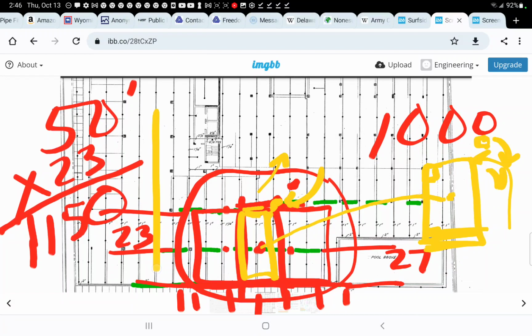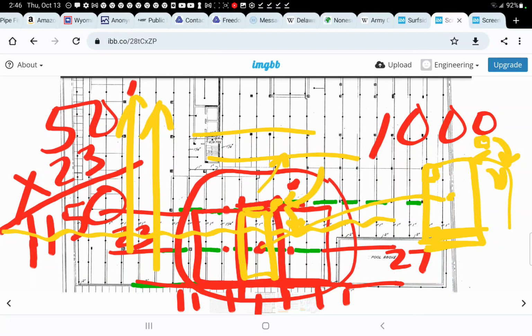Remember, the reinforcement really matters in here, how this is done. It's a number 4 there, number 5 overlapping, high, low. It really matters in the behavior, where it connects, so we can figure out the anchor points and how it's going to deflect. Well, we don't have to do much, because about 3 weeks before, the deflection showed itself, putting it down in this tributary zone here, the butterfly zone, right down the middle.